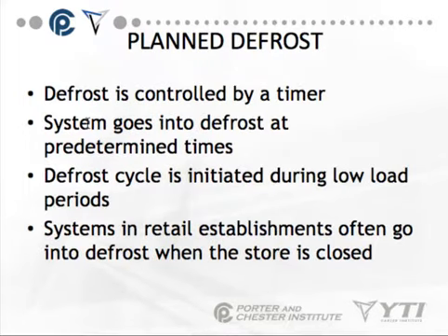Planned defrost just means the defrost is controlled by a timer. The system goes into defrost at predetermined times. The defrost cycle is initiated during low load periods. Systems in retail environments like grocery stores that are not open 24 hours a day most often go into defrost when the store is closed.